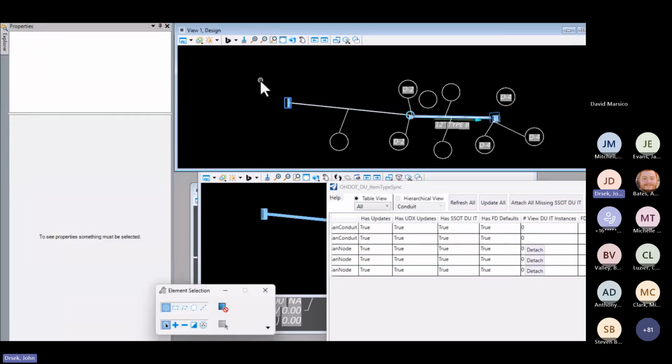I didn't lose any of my properties because I copied all the ones from the one that was good. So all the data you had in there, you didn't lose. The item type data, you did not lose. I want to be clear on that. Everything is still there. There's a little bit of a process, but in terms of nodes, that's all you've got to do: purge all extra instances, reopen, purge all, and you're good on the nodes.